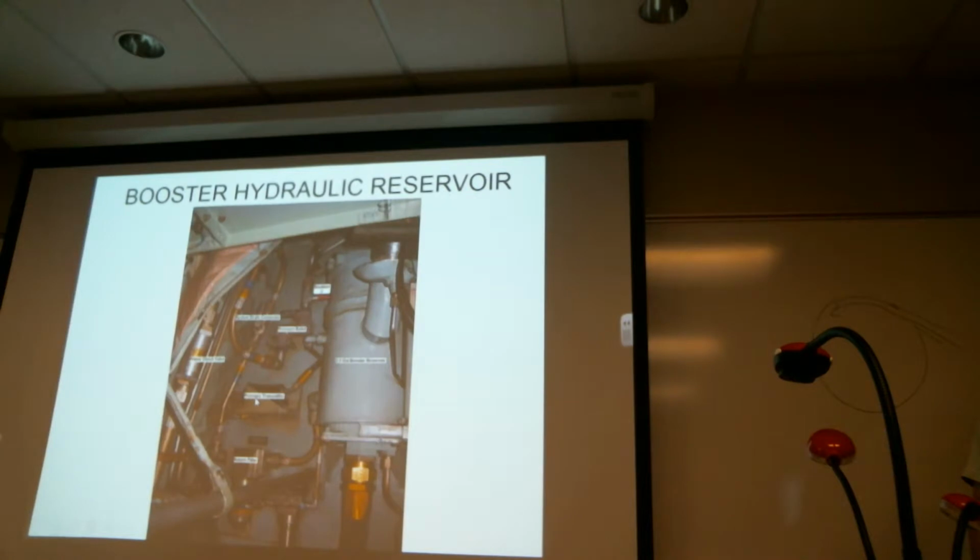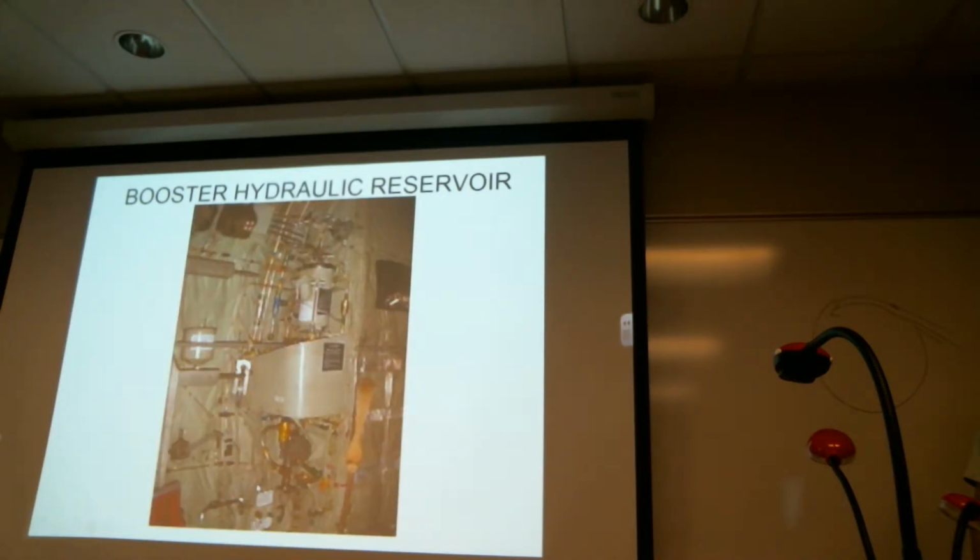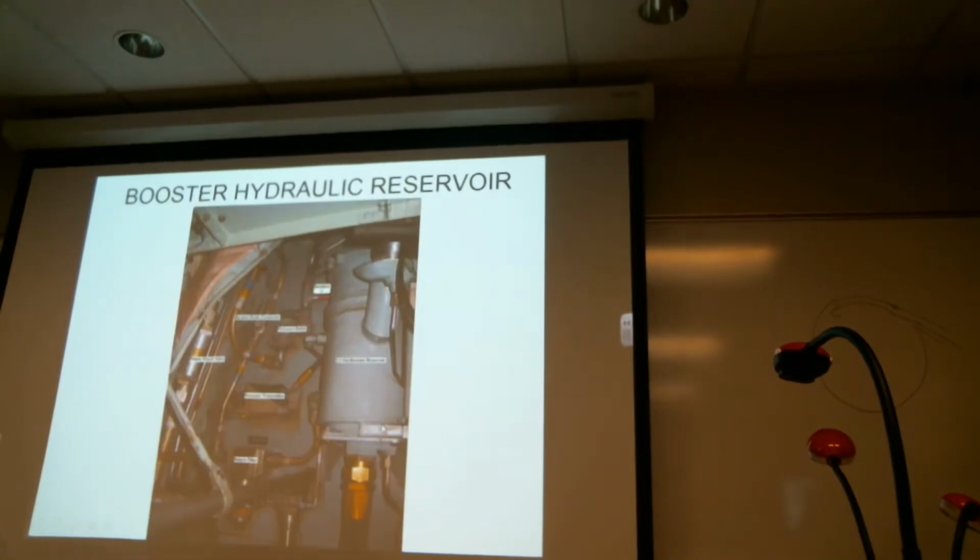They're both vented reservoirs, but nevertheless, this is one method of retaining some redundancy in the hydraulic system. I think their flight controls are partitioned as well. One side of the system sees booster hydraulic pressure, the other one sees utility. So on something like that, it flies pretty high, if it's a vented system.